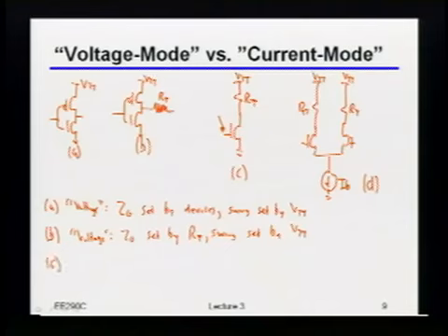Okay, so now, hopefully it should be obvious, but how about C and in fact, of course, also D? What do you guys, is that voltage mode or current mode? Current. Yeah, it should be current mode, right? Because like I said, you'll usually arrange this thing so that the transistor itself stays in saturation. Okay, so this indeed is usually a current mode driver. But okay, so now, again, in that context, what do I mean in terms of the things we've been talking about? So what's supposed to be setting the output impedance here? Yeah, RT is supposed to be setting the output impedance.